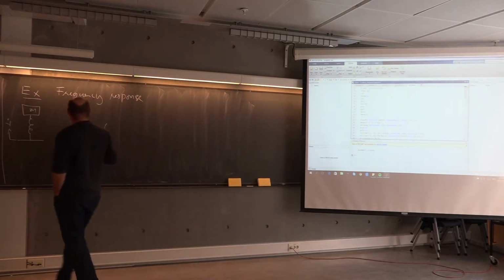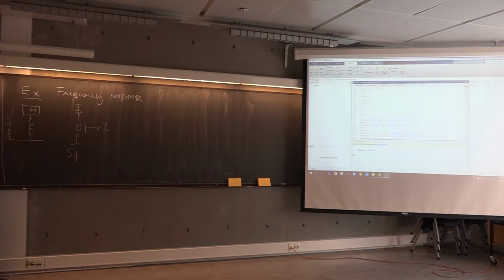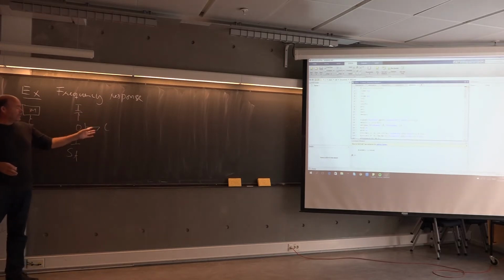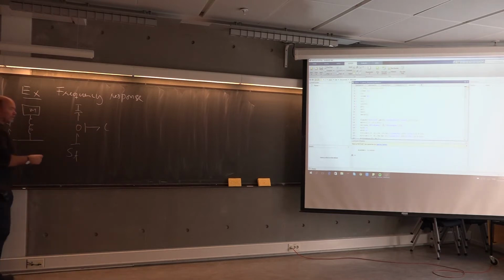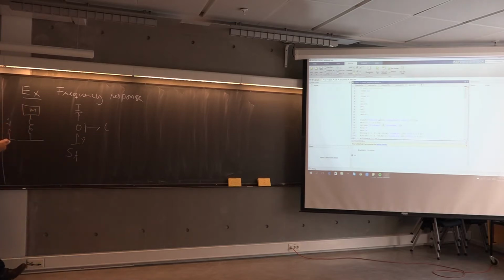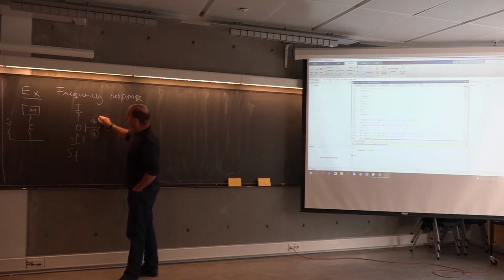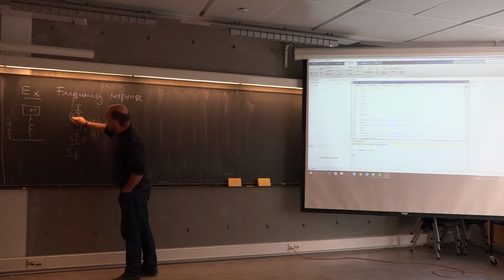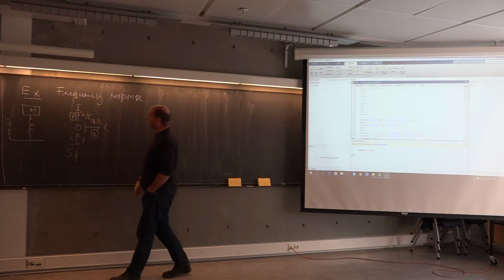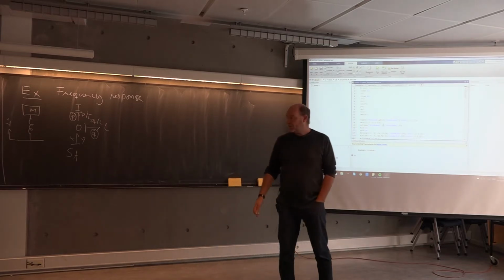So what will be the equations here? You see it's a second order system. You have 2 energy storage elements on integral form, so we will have 2 equations out of this. Here I know the velocity for this plate, the flow source. I don't care about the force needed to do so. Here I will have q dot circle, q over C. Here p dot circle, p over I. And then the entire bond graph has been annotated already.